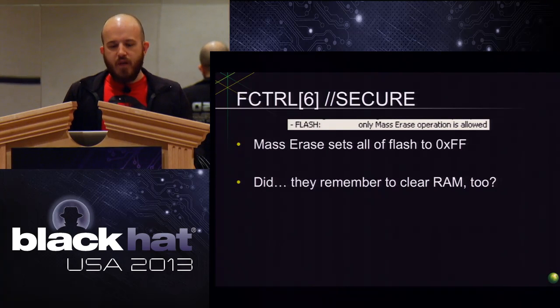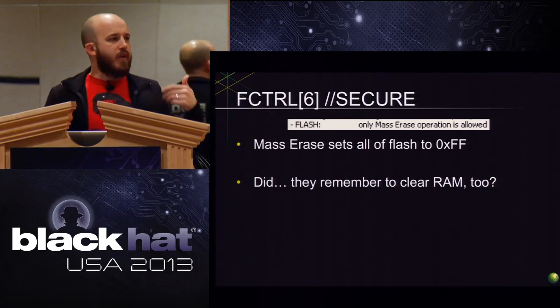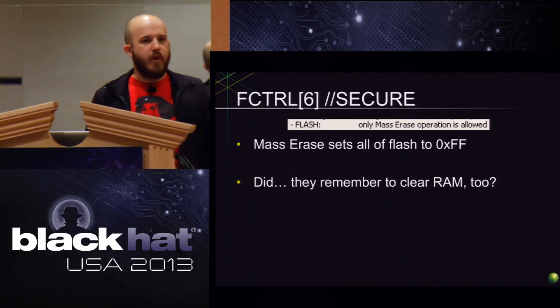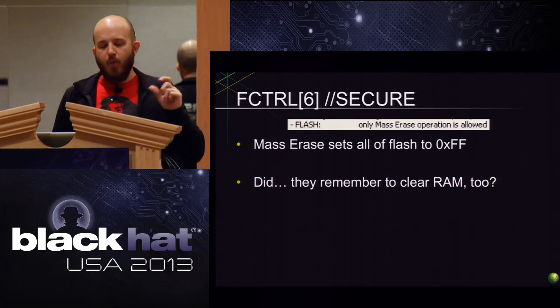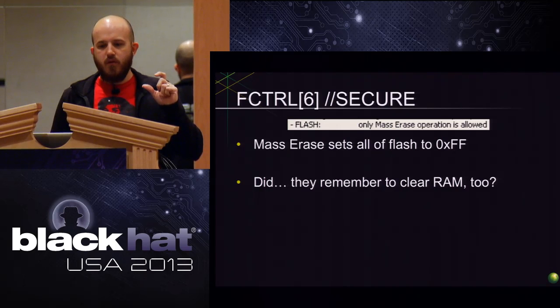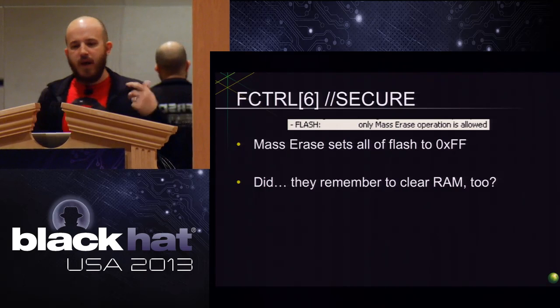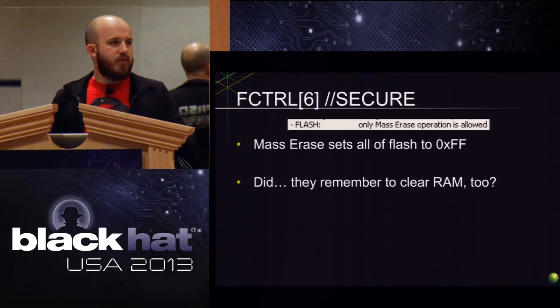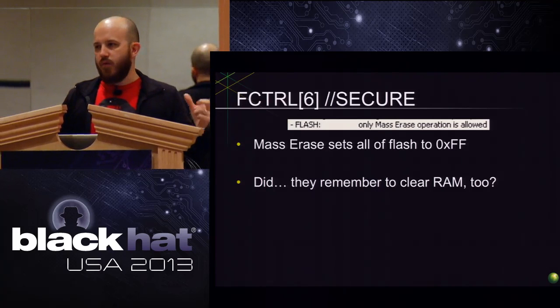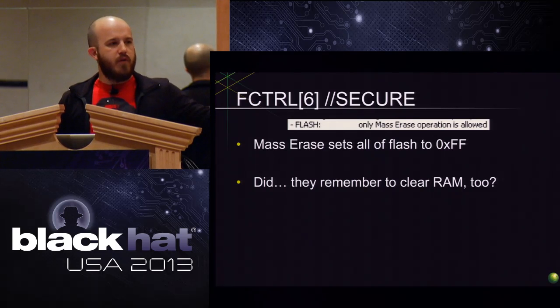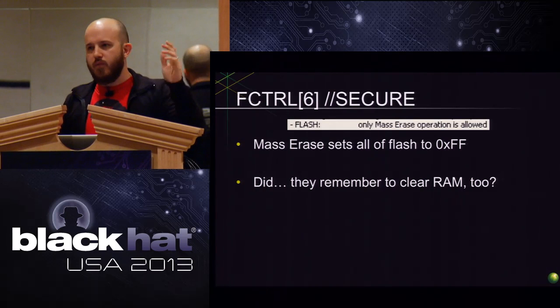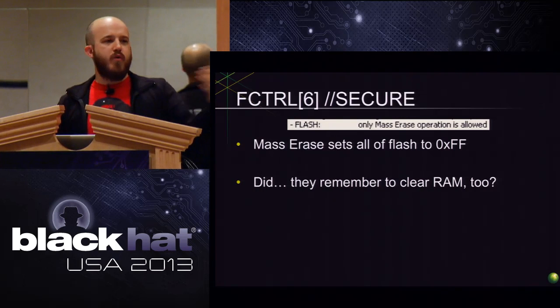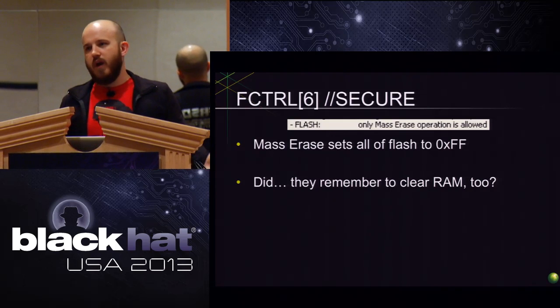The way to unset that. It's not a permanent flag, right? The way to unset that kind of stuff is to hit it with a mass erase, so that you wipe out the code that is setting that in the first place. In the first 30 or 60 cycles, an instruction runs that sets this bit and says turn off the debugging interface. Pre-boot phase ends, and then the debugging interface does not come up.